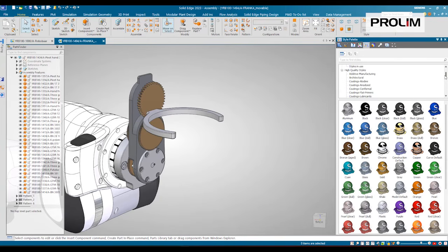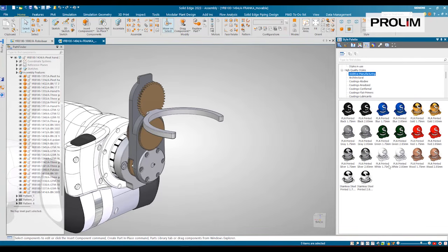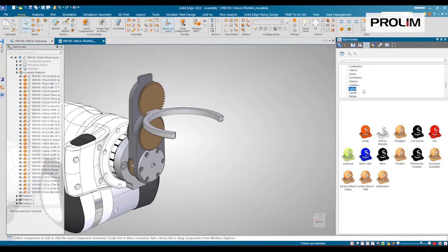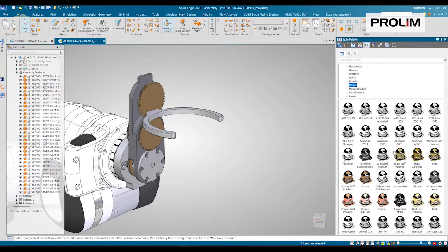to this palette library. So you can see here we've got some architectural, we've got additive manufacturing materials, some PLA types here that we can select from, anodized materials. Let's see, we have fabrics, liquids, a lot of really cool finishes here that we can apply to models directly right here in the assembly model. But let's go ahead and look for our metals here, and we're going to just select aluminum 6061 here, and we'll just drag and drop right onto the part that we just created.